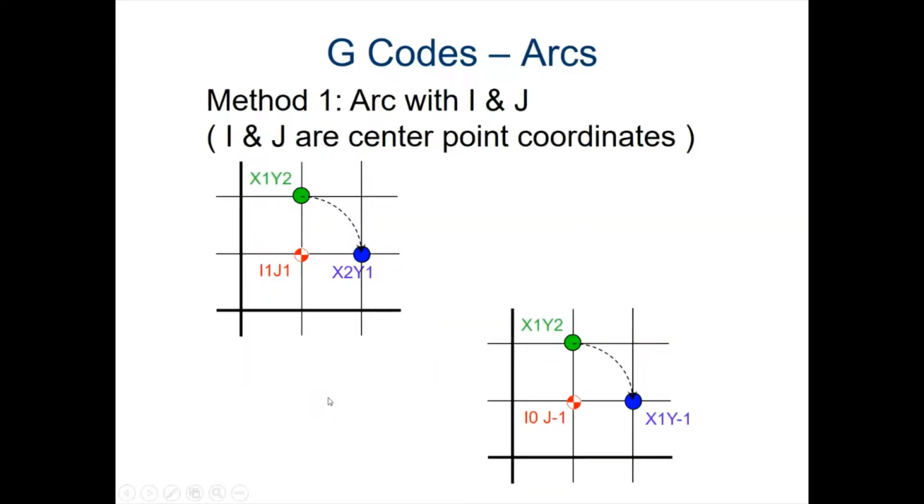All right, so we talked about arcs a minute ago. This is how arcs work. When we have an arc, we're going to have our initial position, we have a final position, and we have a center point that we're going to work around. So when we are putting in our coordinates, we need to identify where we want to go to and what center point we are rotating around. What is the center of the arc that we're working with? And again, these are always circular arcs.